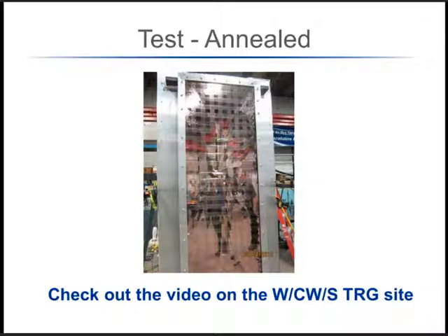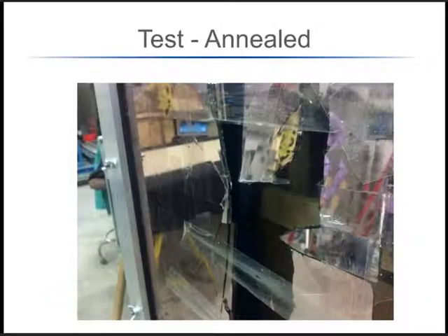But for the annealed, we were very interested in where the fracture origin was. Sometimes that can be tough to track down, but what you're looking for is what's right in the middle of that red circle there. It's a small area. It's very smooth. It's usually a bit of an oval shape. In this particular case, that one ended up being the fracture origin.